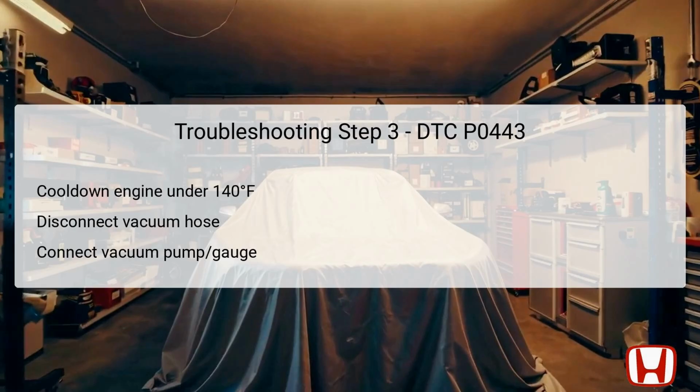Next, turn the ignition switch to the lock position and allow the engine to cool to below 140 degrees Fahrenheit, 60 degrees Celsius.